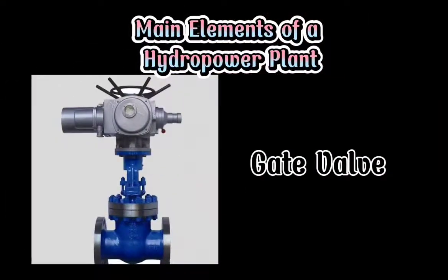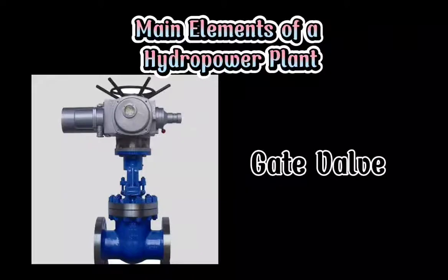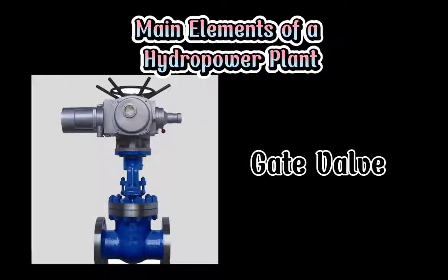Next is the valves and gates. Gates at the entry of the tube casing are typically all that are required in low head facilities to stop the flow and allow for the unwatering of the turbine for inspection and repairs.